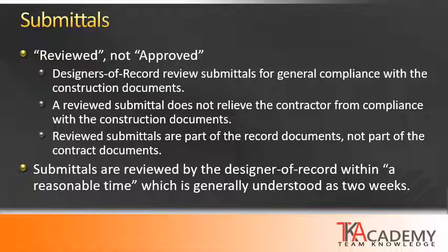Submittals are received by the general contractor, who typically reviews them and then turns those to the designer of record for their review. And within a reasonable amount of time, the architect reviews and returns the submittals. The general conditions of a contract use the phrase "a reasonable time." Generally, this is understood within the industry as about a 2-week period.